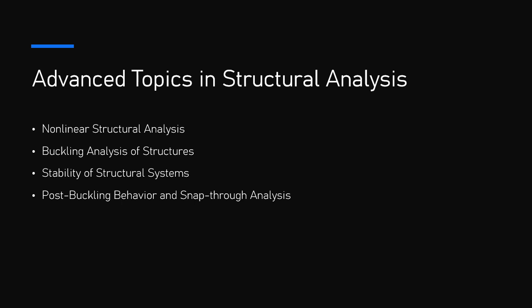1. Material nonlinearity. Elastic nonlinearity occurs when the material's stress-strain relationship deviates from the linear elastic model, typically seen in materials with a large range of elastic deformations before yielding. Plasticity. This is the most common form of material nonlinearity, where a material undergoes permanent deformation after exceeding its yield point. The analysis involves capturing the material's post-yield behavior, e.g., strain hardening or softening.